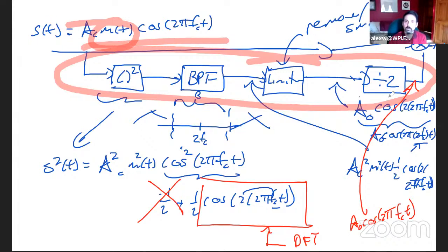What are the learning moments? What is the walk away from this lecture? Well, there's this thing called double sideband, DSB-SC, which almost looks like AM modulation, but doesn't have the delta, which makes it better and worse. Better because it doesn't have as big a dynamic range. Worse because the problem is harder to lock onto. So therefore, enter the squaring loop, enter the Costas loop, which we just saw, which are techniques to be able to lock onto a DSB-SC signal.